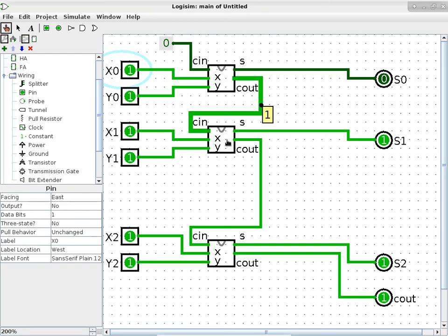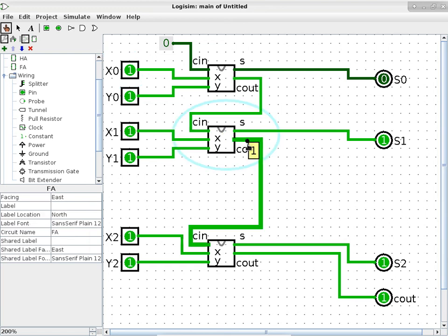The output of this particular full adder is meaningless until this wire has settled down, is done computing, right? But the output of this one is useless until this whole thing is done, which means I cannot look at this output and use it until this particular full adder is done. In other words, we have a problem: each full adder is depending on the carry of the previous full adder before the current full adder can do any useful calculation. They are waiting on each other.